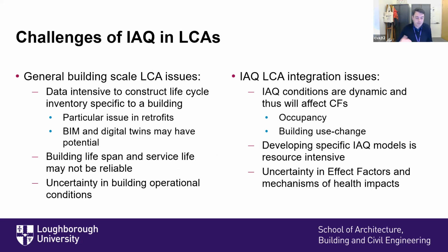So lastly, just to focus a bit on some of the challenges that we're thinking about in the integration of indoor air quality in life cycle assessment. We can separate them into general building scale life cycle assessment issues. Constructing a life cycle assessment for a building is very data intensive, probably primarily because each building may well be unique. The quantity of materials being used, the particular design, its use may differ, how that building is being operated and the operational conditions, which may well affect the energy consumption throughout that 40, 50-year design life of the building.